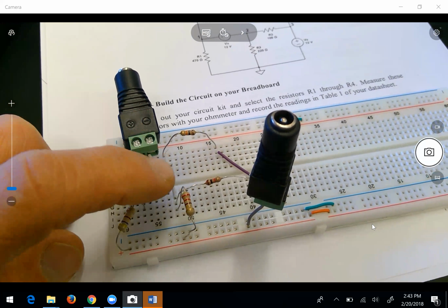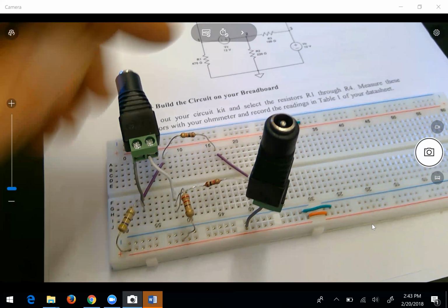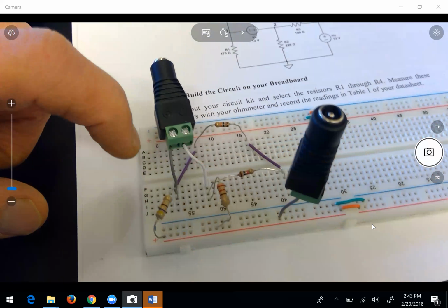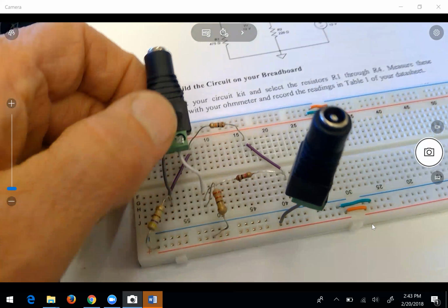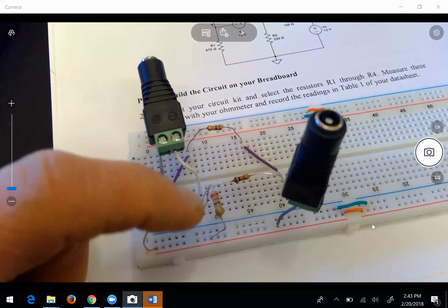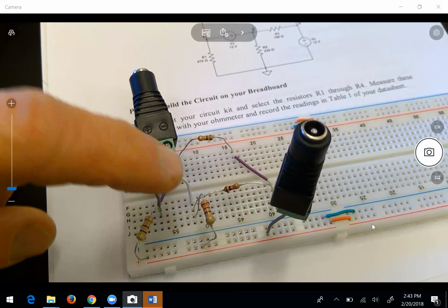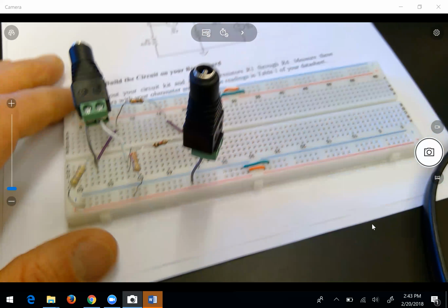And when you do that, you'll see this is asking you to have the high potential side to node 2. You've got the minus side, which is the low potential side, going to node 2. So you have to flip that. You could just flip it, but I would recommend changing the wire colors too, because that will make it a little clearer.